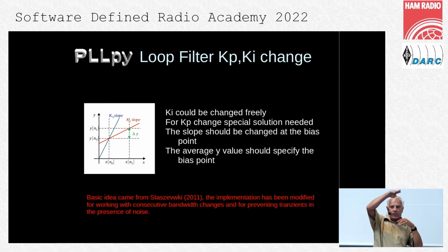at this step there will be a transient, but the bandwidth will be very small, and the settle time will be very large. And that's why you need a method to avoid this transient, and that means that you have to linearize, change the slope of the transfer curve in such a way that the transfer curve will go through the working point when you change the multiplication factor.